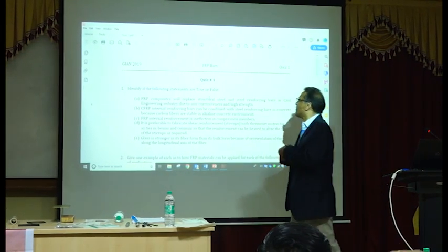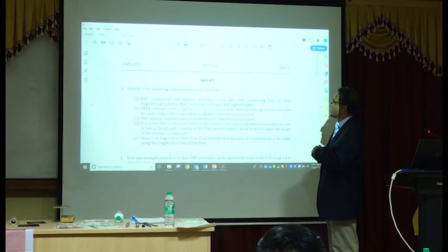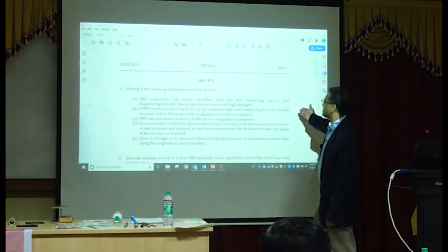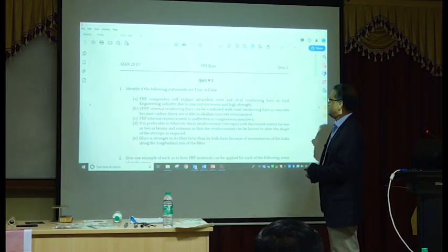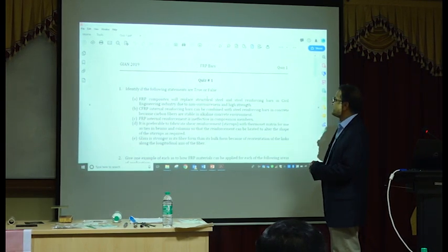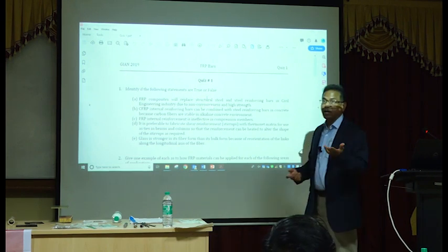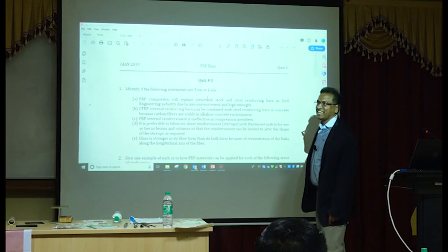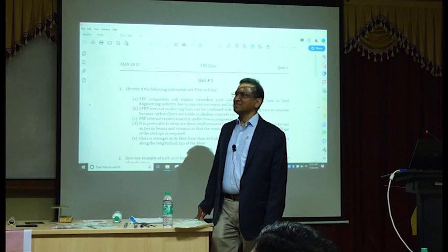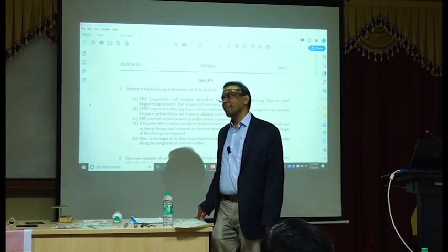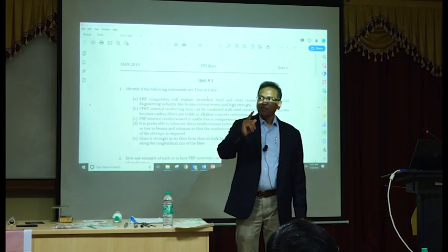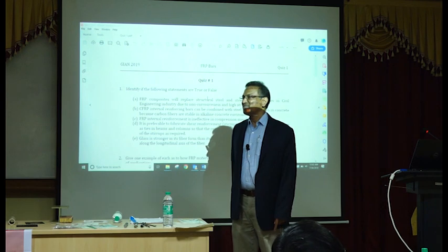Okay. Number 2, CFRP internal reinforcing bars can be combined. We already talked about it. It's not possible. Number 3, FRP internal reinforcement is ineffective in compression. You already got it, perfect. But if a compression member has bending dominancy over axial load, then in that case we can use this FRP bar. You can place an FRP bar, but you cannot use the force from the FRP bar. Does it make sense?